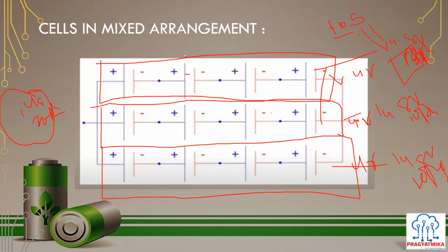It is possible. If you are making such an arrangement out of 10 cells, then taking a 10S BMS and connecting them, it is possible. But the capacity would be very limited. Program the BMS in a way so it knows that the connection has been made in this fashion. If it is programmable. BMS are also of 2 categories. The ready-made BMS cannot be programmed. You can only make the connections, and they will do the balancing. There is no meaning for them in how the connections are made.